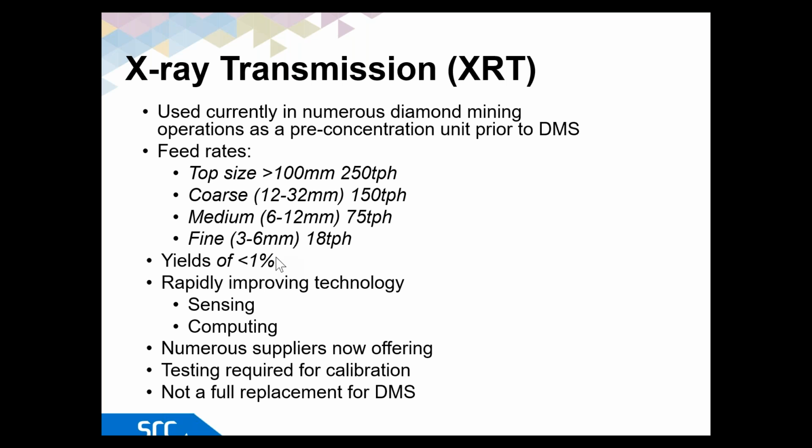The nice thing about XRT is it seems to still be an improving technology, and because of the optics and the sensor bars that are inside the XRTs, the sensitivity of these things is increasing, and as that increases, the number of pixels then increase, which can push those resolutions down to those finer size fractions. But with that, you're also introducing more particles. And as you introduce more particles, that's an exponentially high number of calculations, or decisions it has to make on what to eject. But that's exactly where the technology is moving.